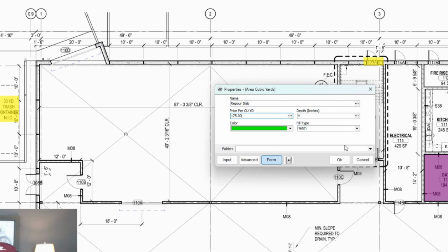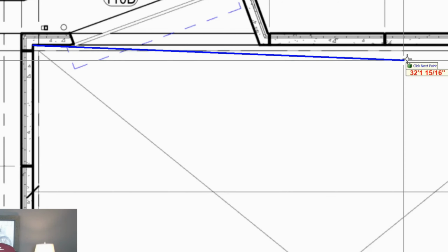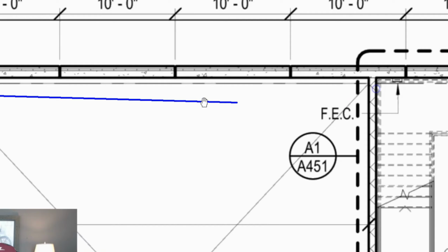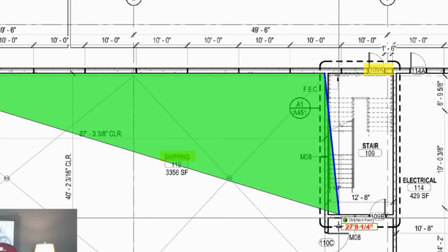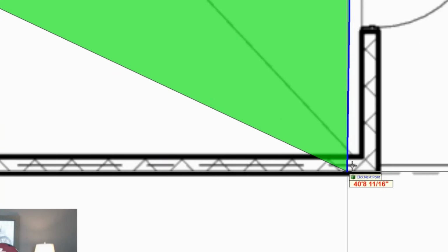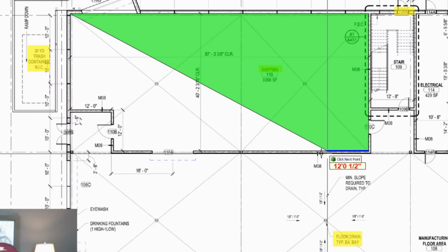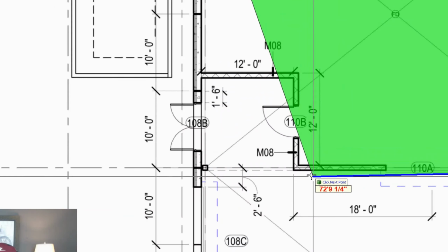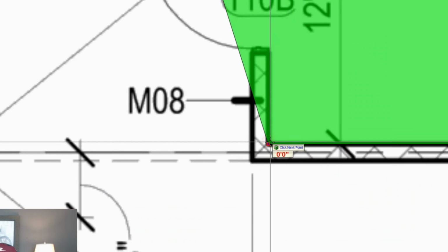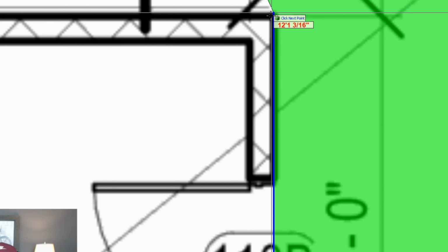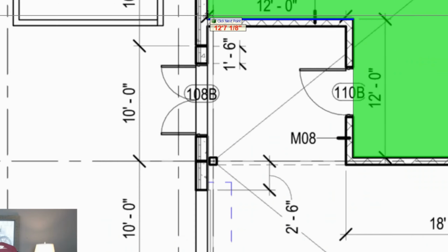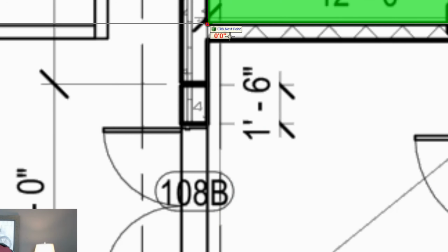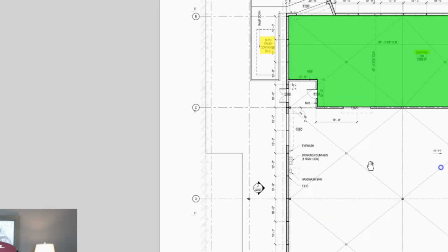And I'll leave the hatch area okay. I don't need to do anything else. And I just start my takeoff here and go through here. Remember, you're using 2 fingers. Right clicking allows you to move around the area. Left clicking allows you to click the points. And then your wheel allows you to zoom in and out. And I promise you, you'll be able to do it as fast as I do in no time.